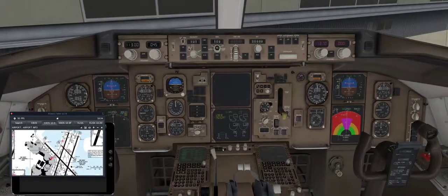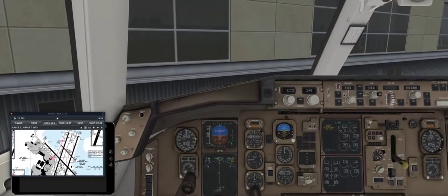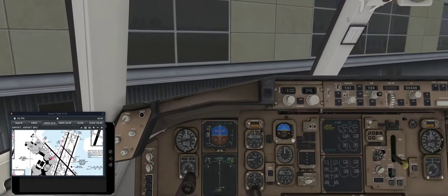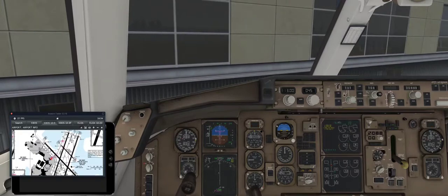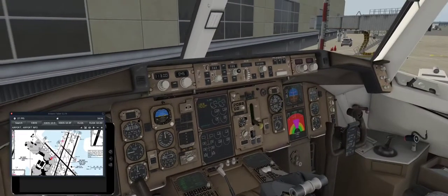Getting in the engine start position with this screen viewed. Push this left button until you have both these views, because you're going to need N2 to properly start the engines. Once he's connected, he'll tell us it's okay to start the engines, and that's when we'll do that. We're going to reset the auto land system, because we're obviously not auto landing at this point.